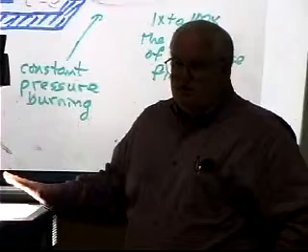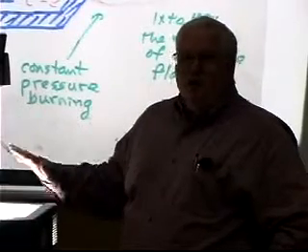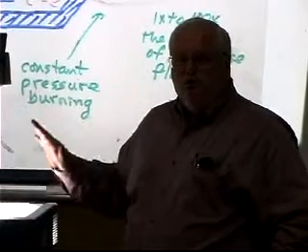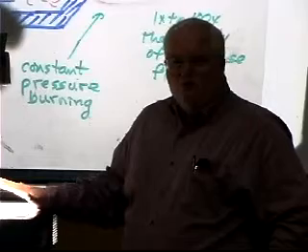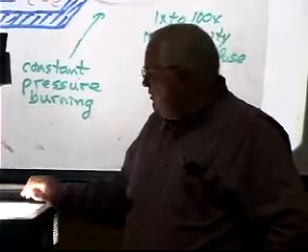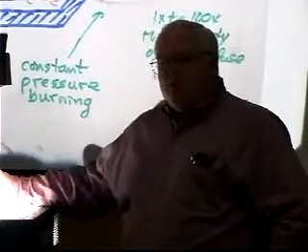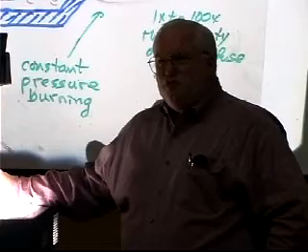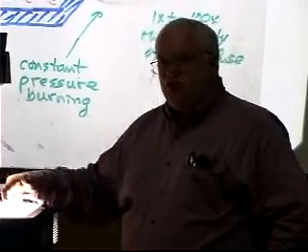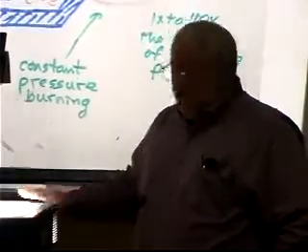So that's a pre-mixed flame. It's designed to give you a nice blue flame, no excess soot, which is going to turn the flame yellow, and things like that. You're going to get a higher burning velocity because you have a higher temperature. You're at the stoichiometric ratio as compared to a diffuse flame. You're burning at constant pressure, and so it's not too loud.